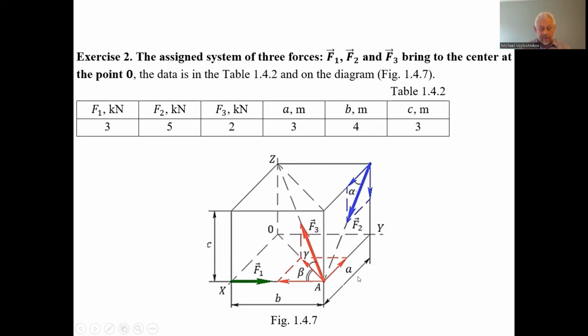So the force F3 impact on the projection of the main moment on x-axis is this one force, F3 magnitude multiplied by cosine beta multiplied by sine beta, and oh, I'm sorry, this one does not cause the moment relative to x-axis, as this direction is parallel to x-axis.